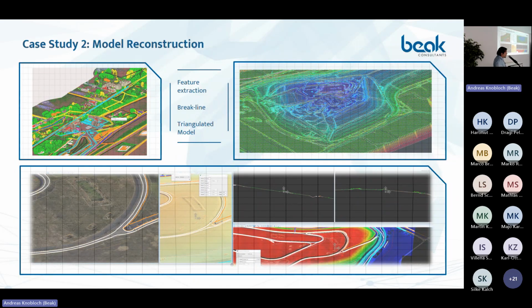Here is the digitalization in 3D in the isometric view, how it goes, roads and different elements. As you can see here, the buildings were extracted automatically from the point cloud classification, and we extracted most of the break lines automatically also from the classification of the point cloud. And then the other part was done manually because it cannot be done automatically.